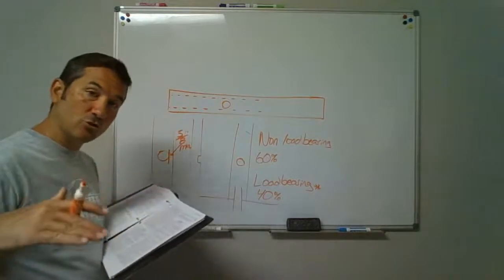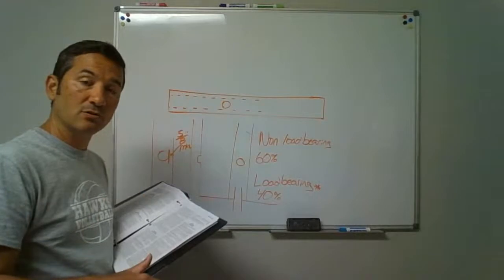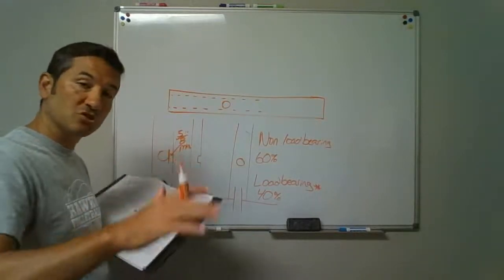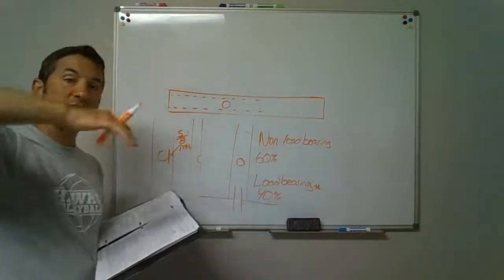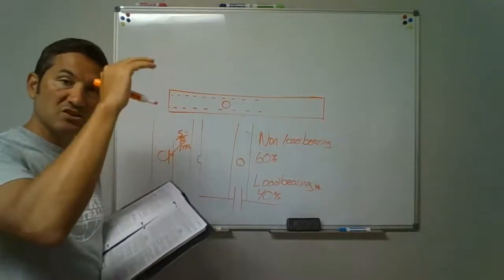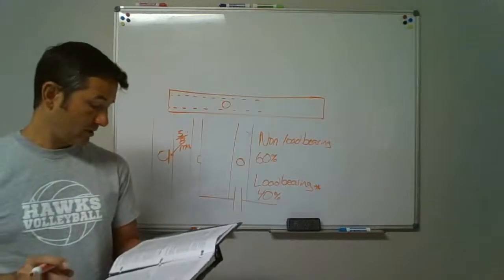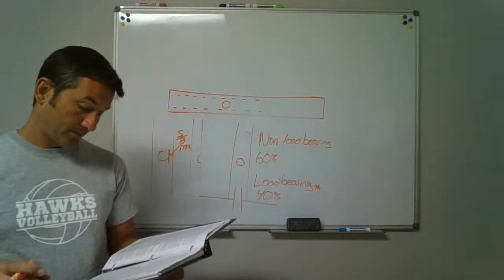We don't want to have a draft going from low to high, and the fire started off underneath in the crawl space. If there's a draft coming up through, it'll suck the flames right up and spread the fire through the main level and up into the attic. So we fire caulk between floor levels, from floor to ceiling, all around our pipes, drain lines, water lines, all of that. Okay, and we'll be doing plenty of that.